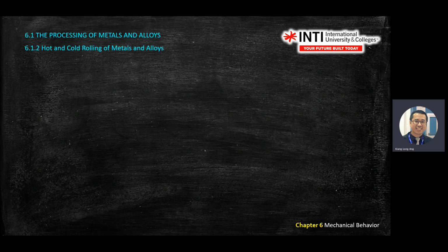Previously, in chapter 5, we went through the solidification process. Just now we introduced you to the die cast. In the solidification process previously in a mold, we told you the types of grain that you have. On the wall here, you have a uniform grain. But at the center here, you'll get a longitudinal, a long shape of grain. So this is part of chapter 5. This also will tell you the structure or the properties of that one.